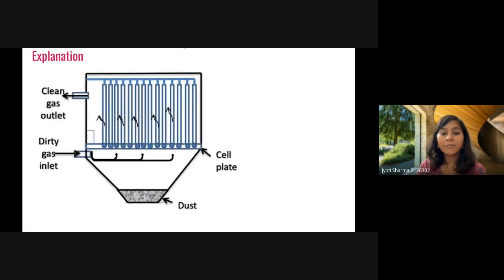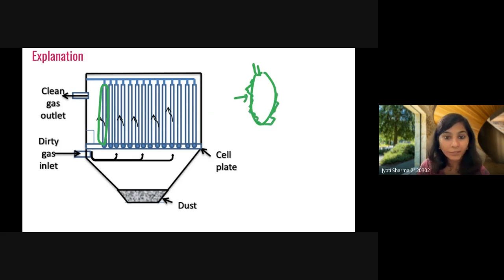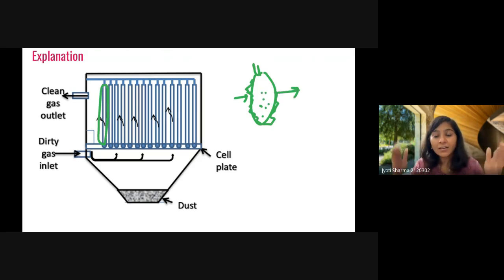This is the fabric filter I was talking about. This is your fabric filter, something like a bag. Because you know that the fabric is woven, whenever there is gas, that gas will have the particulate matter. That particulate matter will be deposited into these bags, and then the gas will come out. We have thousands of such bags in a single machinery, right?